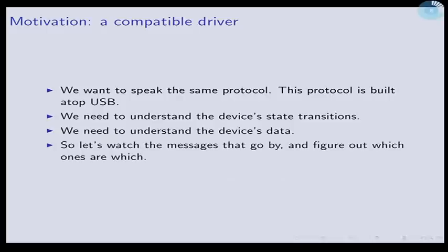So the obvious thing to do here is, these are devices that already have a driver working somewhere that is used to interoperate with that device. So let's just watch exactly what's said back and forth between the host and the device when they're in normal working order, and figure out what's the data, what's the state, and how we can encode our own data or state accordingly.